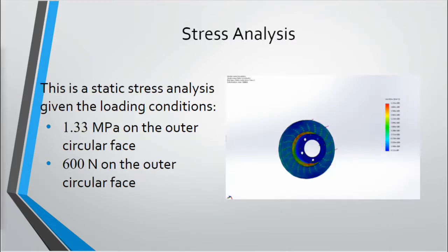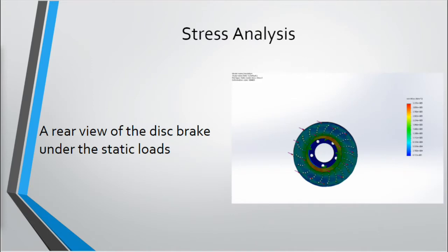Here's our static stress analysis. It has been given two loading conditions of 1.33 megapascals on the outer circular face, simulating the contact of the brake pads, and 600 newtons on the same face but in the radial direction to simulate the frictional forces. A rear view of the disc brake under those loads.